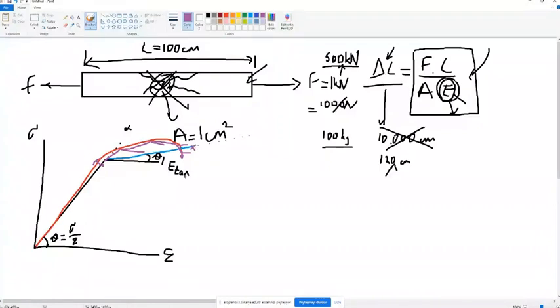You have to say that here is the breaking point, point of failure, failure parameter, to the computer, and the computer will understand when your stresses or strains come closer to this value. The results can be seen in the finite element screen closely to the real deformation.